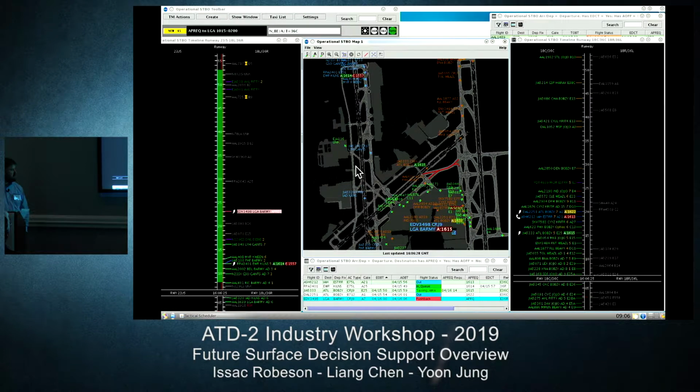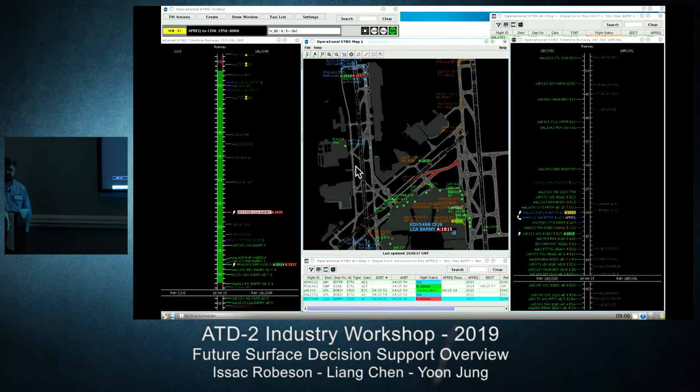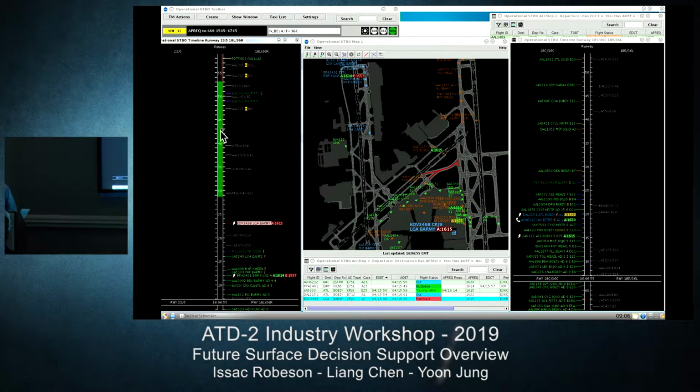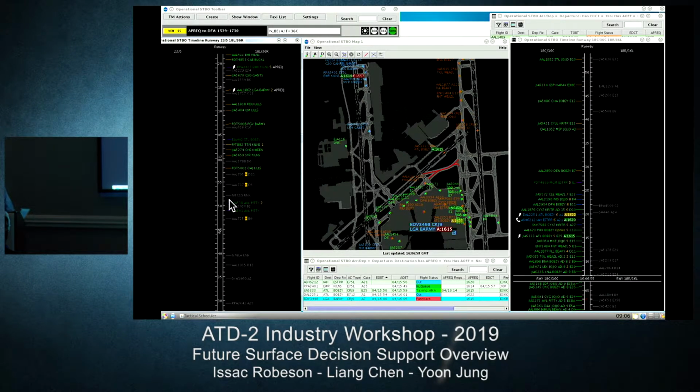So he's setting an unrealistic push release time, so it's going to say, no, we don't actually think you can make that time. That just gives the TMC a quick view. They can see that flight is probably not going to be able to make that time, and we need to go ahead and renegotiate. Because they have the red space, green space, they can see what times are available and can make an informed decision about when the flight can actually get to the runway, and whether we want to shoot for an aggressive time, or whether it's worth being on the safe side.